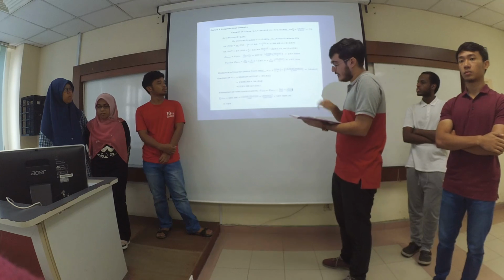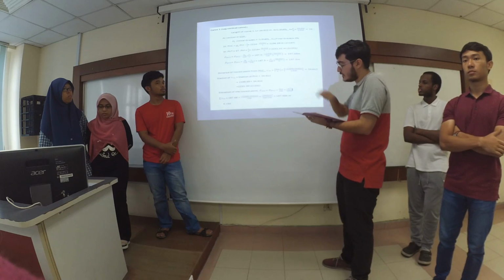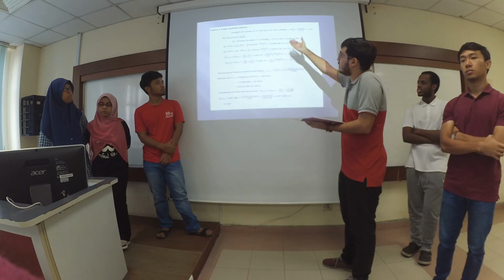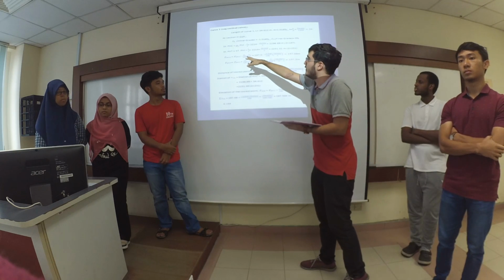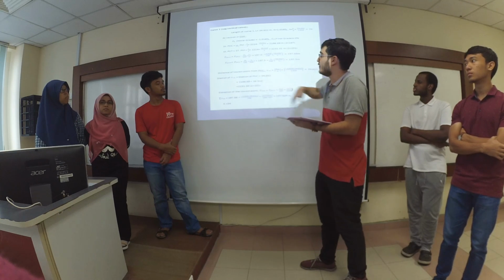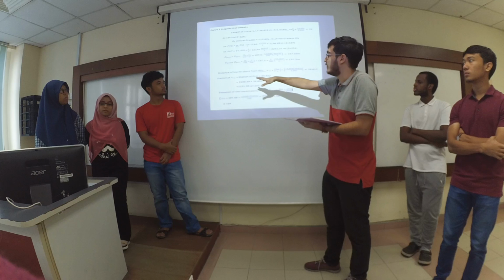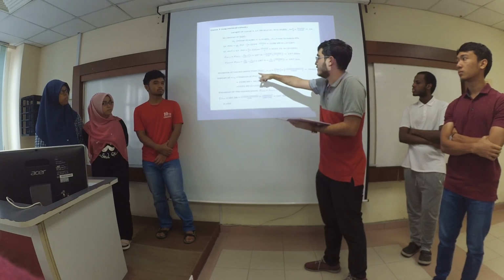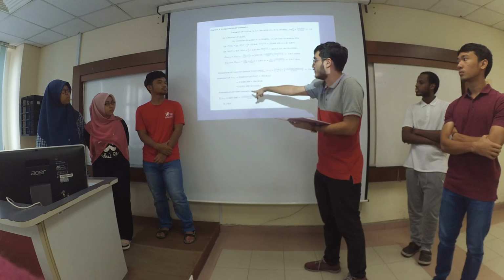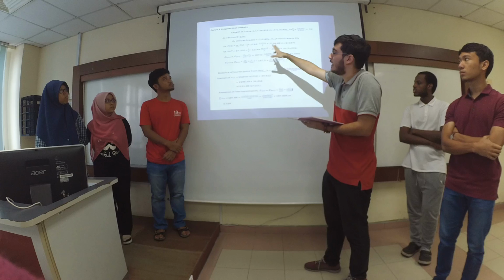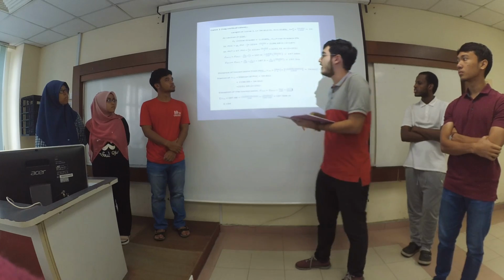We already set the elevation of predetermined points in each of the vertical curves, so we have the respective PVI values. So this is the calculation that we did for the station of PVC, station of PVT, elevation of PVC, elevation of PVT, the distance of the lowest point from PVC, and also the station and elevation of the lowest point. And the same procedure is done for the crest vertical curve, except this is the distance of the highest point from PVC.